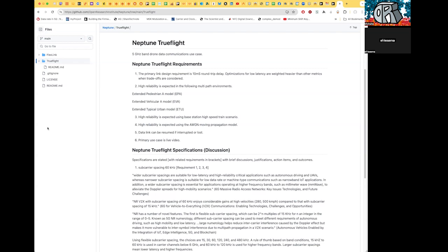I was thinking about that. If you actually wanted to design a test for two, a lot of times I see those kinds of tests in the specification. The specification isn't just how you're going to implement it. That's where the verification step is, they try to put numbers to something that's a little higher level in the requirements. So like high reliability, you can phrase that in terms of I want such and such a bit error rate when there's such and such a maximum Doppler shift, and such and such a signal to noise ratio over such and such a range.